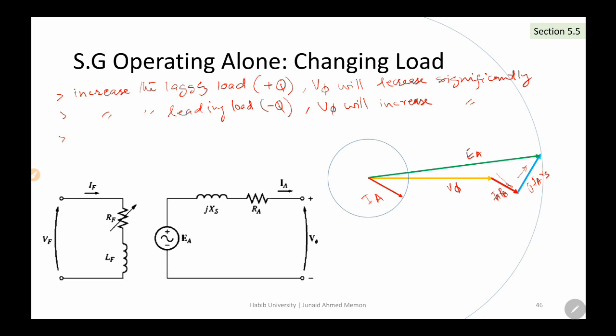And if you increase the resistive load, in that case V phase will still decrease, but not so significantly as compared to the inductive load. But still there will be a decrease in the V phase, as we saw in the phasor diagram of the resistive load as well.